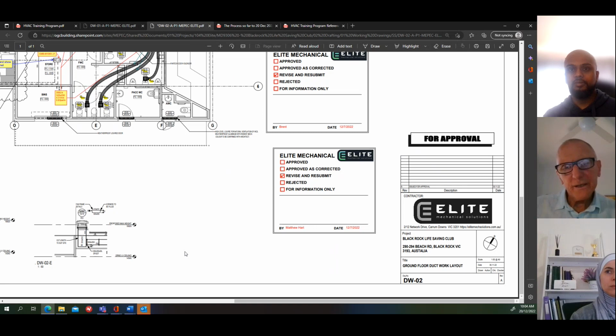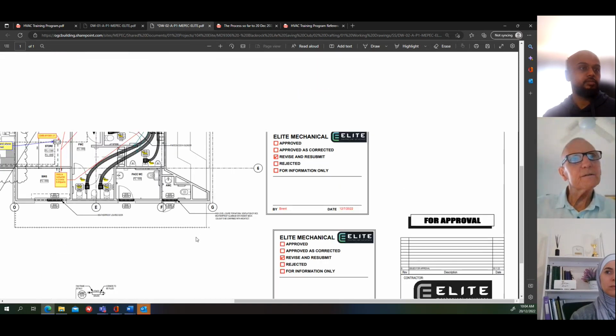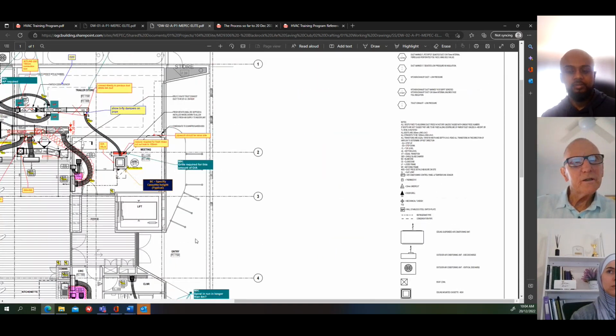But you're going from one to the other. So I wanted to point out to be aware of the changes from the design drawing to a workshop drawing in the actual duct size on the drawing. Even though it's the same airway size, it's a different dimension because of the insulation.